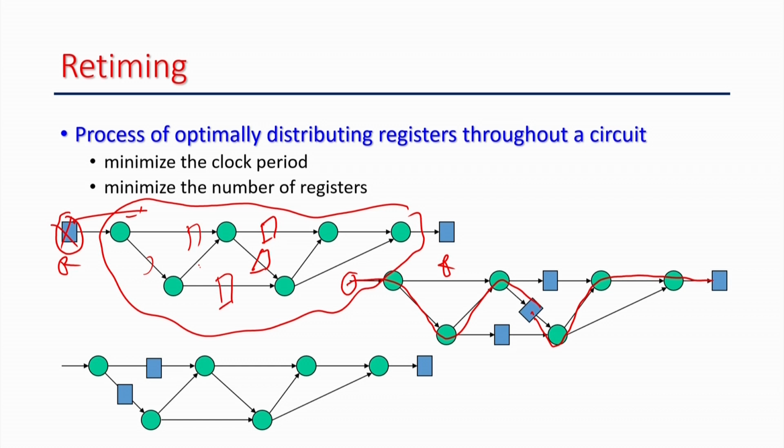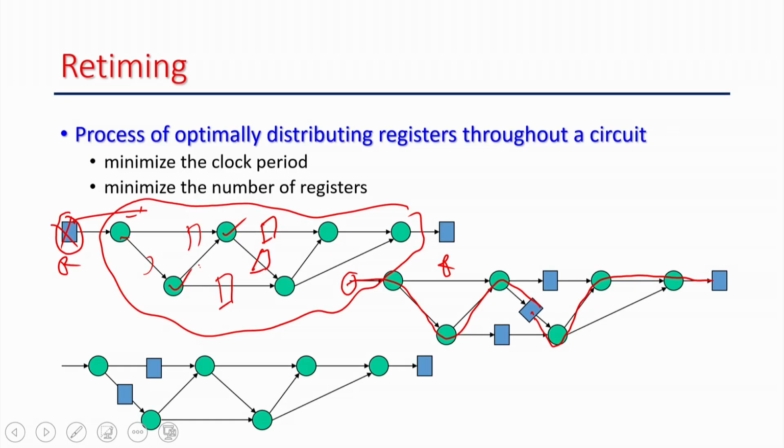Your circuit may have say 10,000 or 20,000 resistors, a million gates, and maybe more than that also, right. So, doing these things physically or manually is not possible. So, we have to automate this process. Given the circuit and the combinational delay of each node, if I give it to the tool, how do we automatically do this retiming, so that finally I can reach from this circuit to this circuit? That is what we are going to discuss in more detail here.